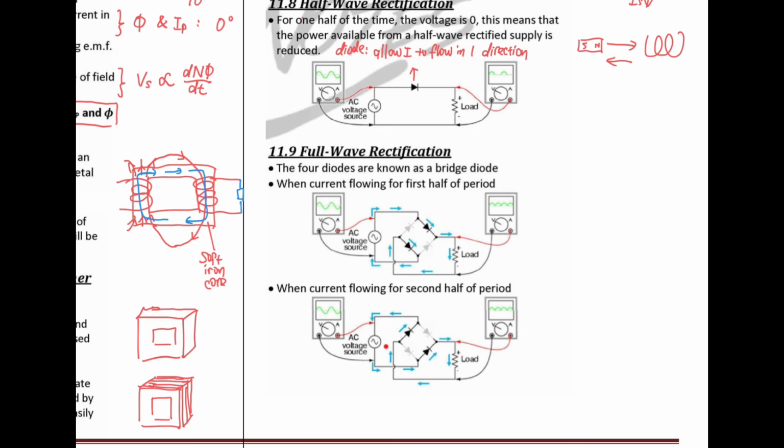Then this repeats again, and the fourth one, which is negative, becomes positive. So it seems like we managed to keep all the wave, and at the same time, we change all the wave to the positive direction, which is up to down, the same direction. This is quite perfect already. It seems like the alternating current has become current in one direction, which is direct current now.